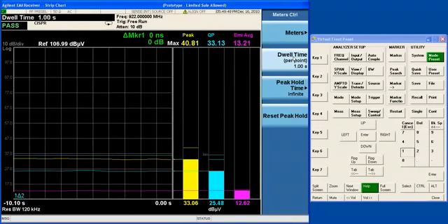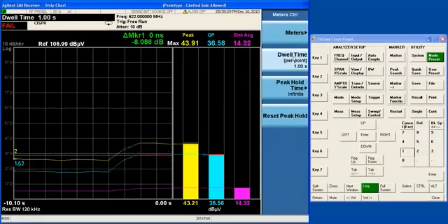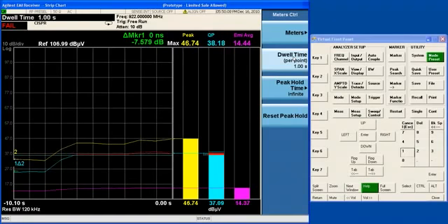But that isn't the main thrust of the strip chart measurement. The main thrust is to use a high resolution, a short dwell time, and measure your signal dynamics. So if you're trying to make CISPR compliant quasi-peak measurements, use frequency scan. If you're trying to look at your signal dynamics or capture signal history, use the strip chart.